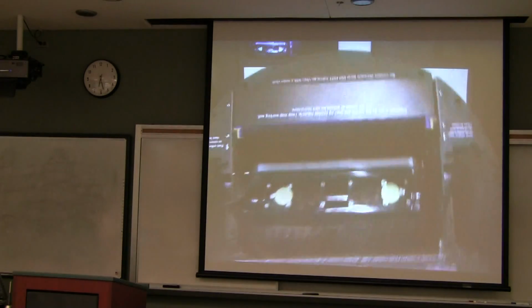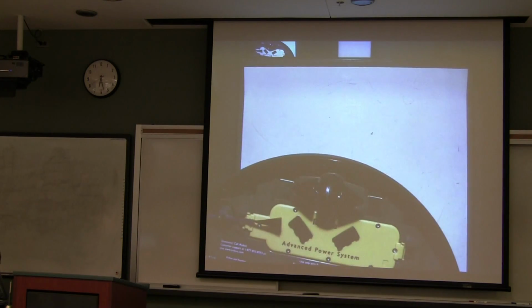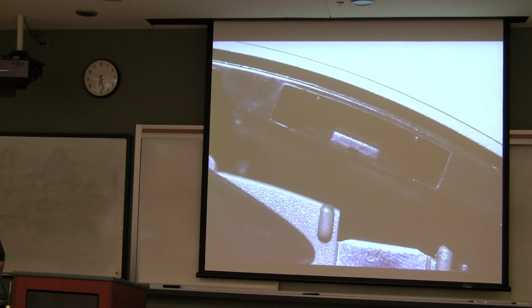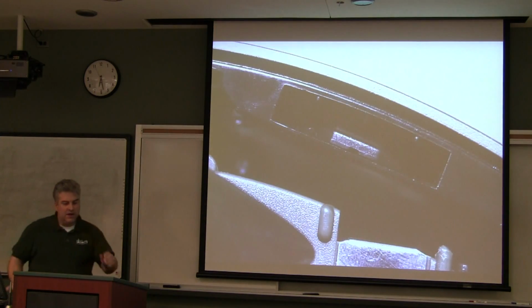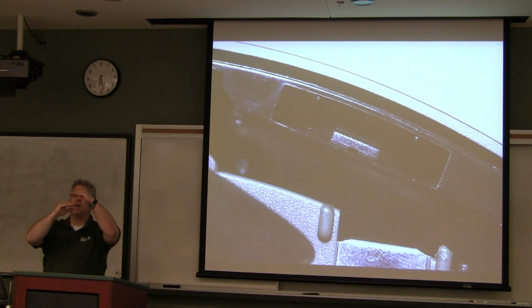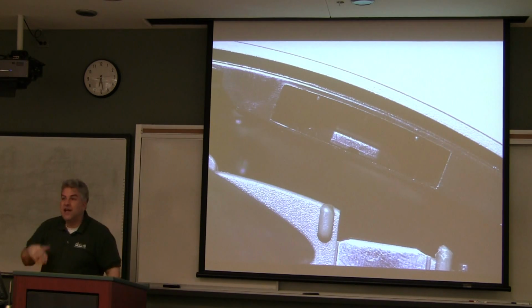Let's see, what other do we have here? This, under here, you will not be able to see as well unless I zoom in. And I really can't tell too well. In here, which you can't see well, is an infrared light and sensor. What do you think that would be for? Stairs. So it keeps you from going downstairs. So it looks for a cliff when you're going from half an inch, half an inch, half an inch, 6 inches, you know, really long. And it'll keep it from going forward. All right.